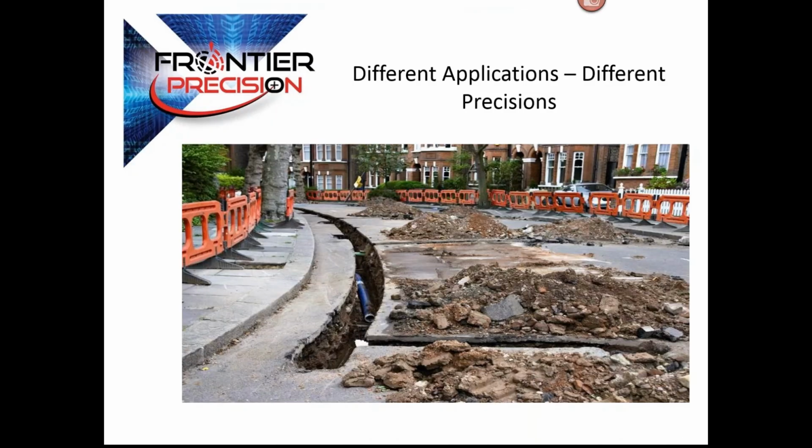So what this picture is trying to show you is that today there are many types of GNSS receivers, and there is a trend to bring your own device. And some of these devices can also use cellular-based corrections. If you're using a BYOD device today, that standalone GNSS or GPS receiver is probably 5 to 10 meters of accuracy.